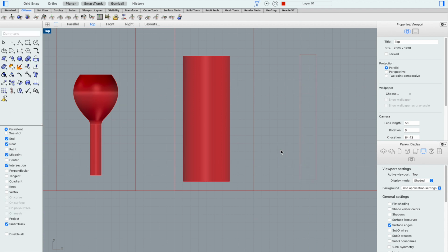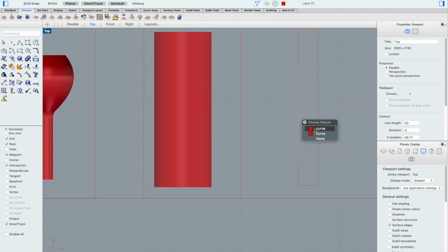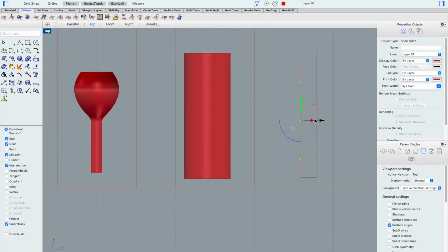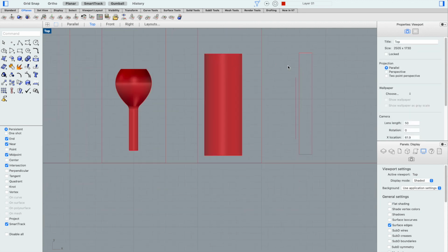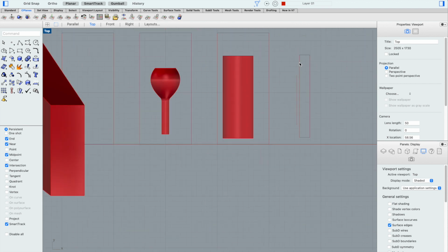From there to there, the length of the axis is arbitrary. And if I know that I want that inner hole to be an inch wide, then what I need to do is move that in that direction, or that direction, that's fine too, by 0.5 inches. Actually, that moves it to the inside, so we're going to undo that. Negative 0.5 inches. Because I want that inner circle to be hollow, I need to make sure I'm giving that radius a half an inch of offset, and that's going to give me a 1 inch hole.